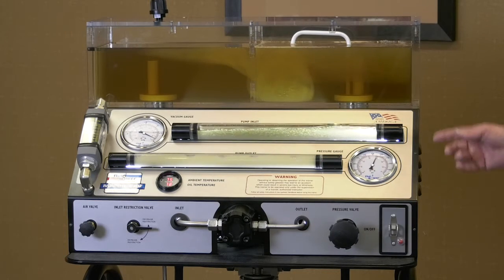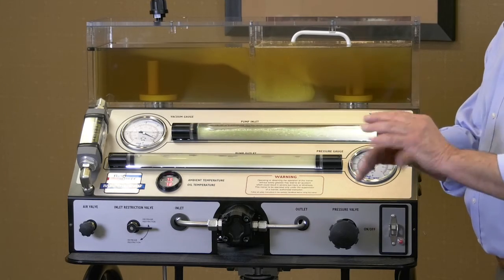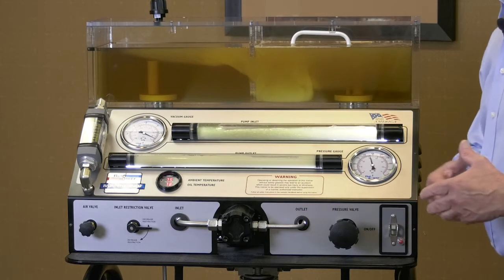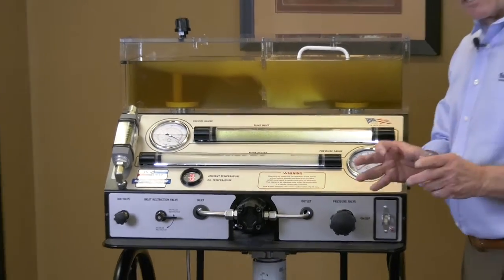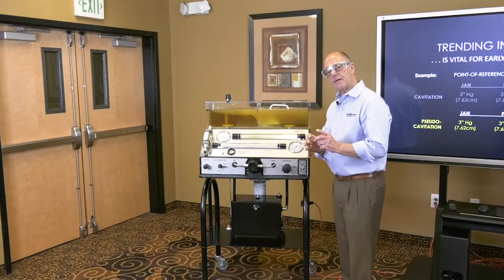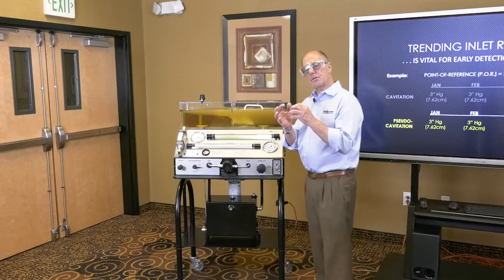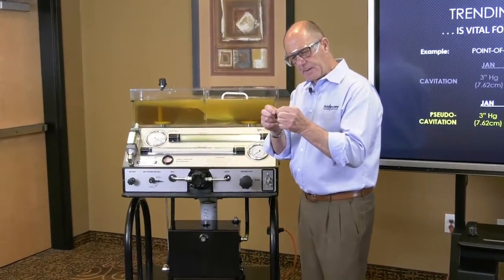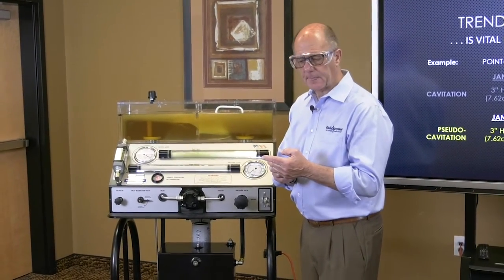Bear in mind that whatever you see in here represents what the oil will look like throughout the hydraulic system. That's why we call this a systemic catastrophic condition. So let me back up. Cavitation is a systemic problem because when the implosion occurs, it pulls little pieces of the pump out and feeds them downline into the system.